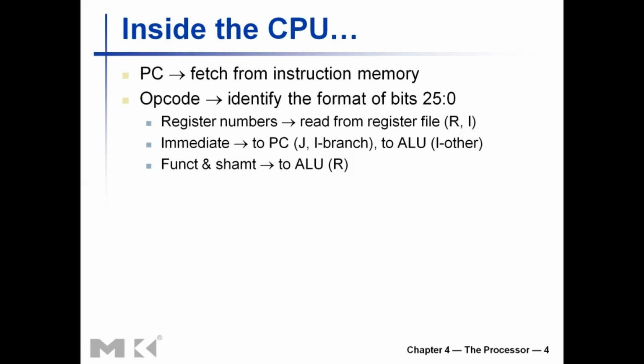So keeping the opcode width as 6 bits for all these different types of instructions makes the CPU implementation very simple. You only have to look at the first 6 bits to decide what the remaining 26 bits are supposed to be, right? So to interpret the remaining 26 bits. So it makes the CPU's implementation much simpler.